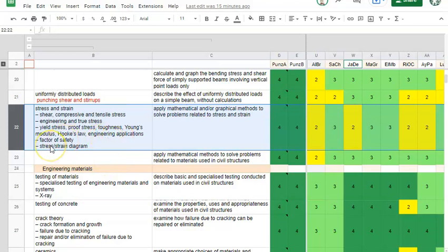Engineering applications of all of these things, we can use these diagrams to make good predictions about whether or not things are going to be strong, whether or not things are going to resist impact. The main thing that we're interested in though is the yield stress. The one exception to this is that if you need to punch a hole through something, we don't care about yield stress, right? If we need to punch a hole through something, it doesn't matter if they say, I give up, I yield. No, if you're going to punch a hole through something, you care about their ultimate strength, right? Because they're going to keep fighting if you're going to punch a hole through them, right? If you don't give them an opportunity to retreat.